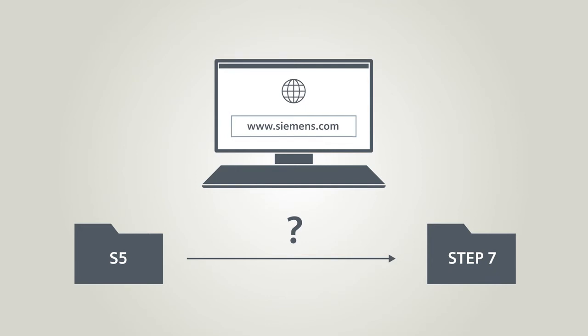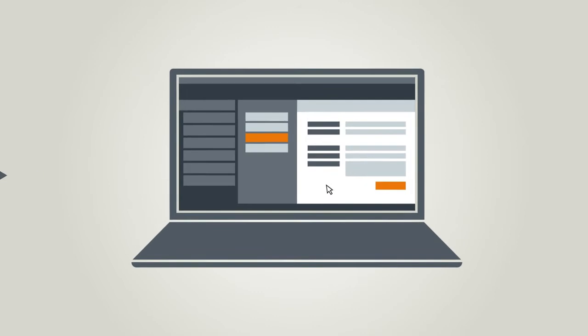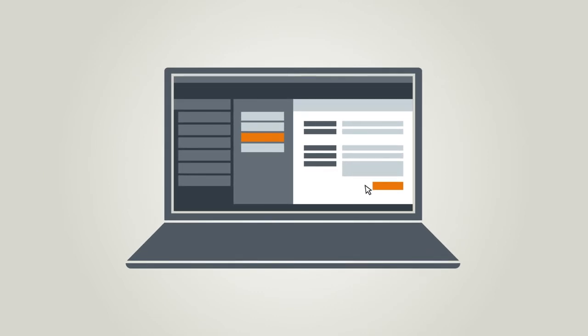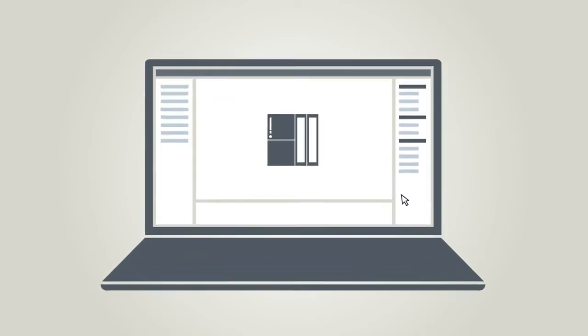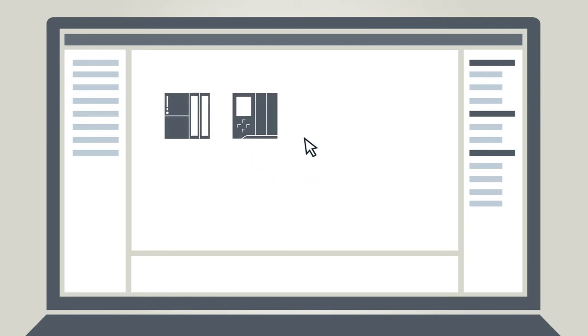The Step 7 project is converted into a TIA portal project using the Migrate Project TIA portal function. Use PLC migration to migrate a PLC program within the TIA portal to an S7 1500 program. If a program cannot be converted without errors, the result can be improved by taking appropriate preparation or follow-up measures.